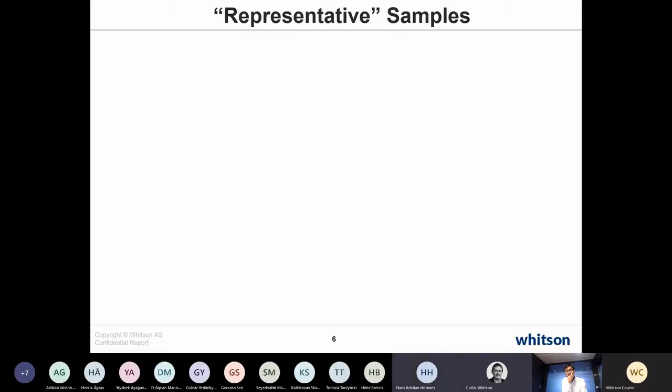But even for high temperature, you might get exceptions where you have high H2S, high CO2 content in a high pressure gas system. That might be a case where it would be the exception, because you get so much partitioning of those components into the water coming into the gas phase that it could have an effect. You know, there's always this 0.1 or 1% of the cases where it might have an effect.